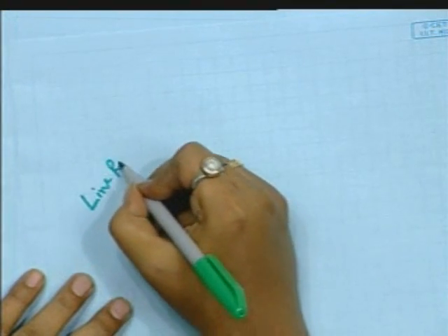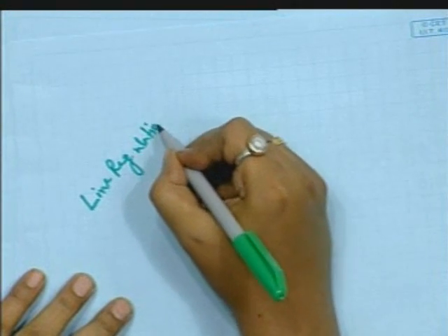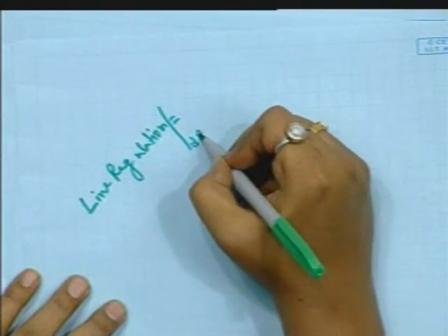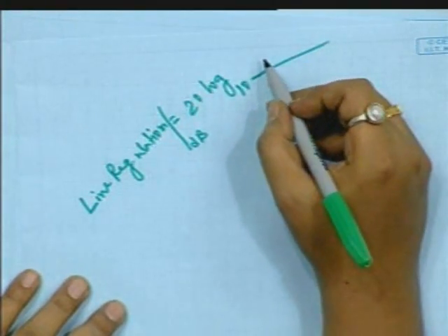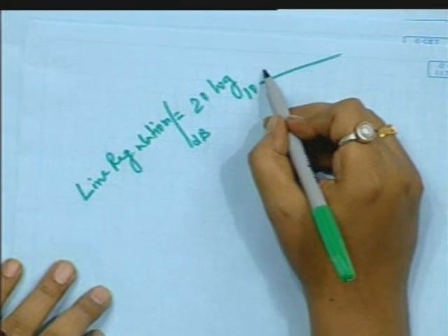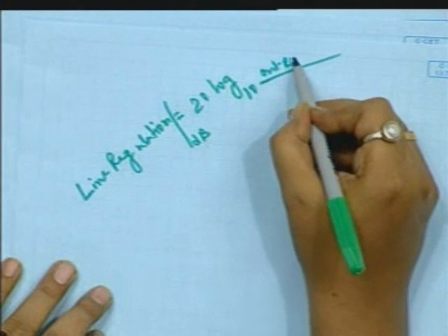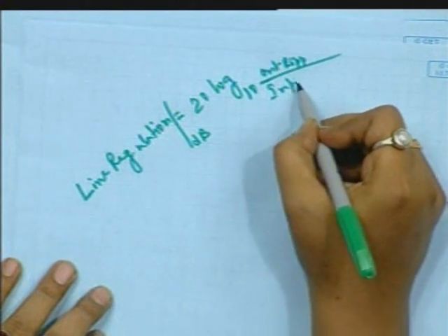Line transients also come into the same category. Line transient means the capability of regulation by the LDO due to the variation of the line voltage, that means supply voltage. And here I will define one term, that is the amount of regulation, line regulation in dB, which can be given as 20 log base 10 of the output voltage ripple by the input voltage ripple.